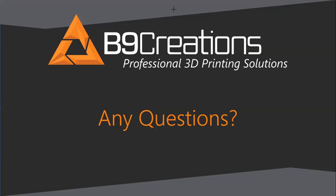Thanks, Cody. A lot of people wonder where they can locate the firmware update on the Create software. If you're in the Print Manager and you go to the Settings page, scroll all the way down to the bottom, you will see the firmware, the most recent firmware that's been released, and that can be transferred to your USB and then to the printer.